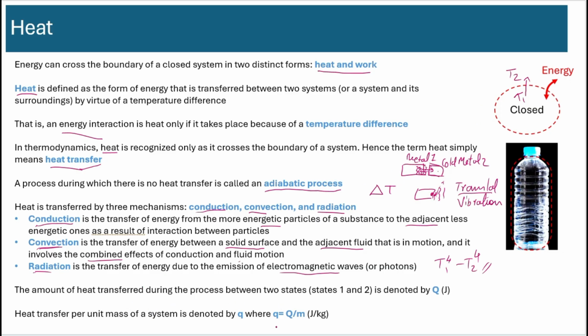And typically the symbol used for heat transfer is Q. Do not confuse this with quality in CoolProp. In CoolProp, there is no function for Q for heat transfer, because this is not a state function. It's a path function.